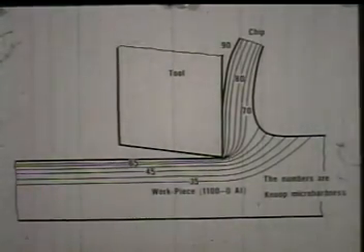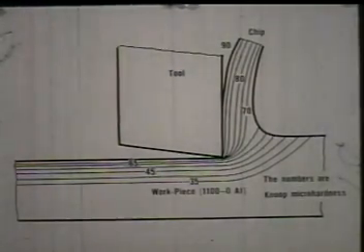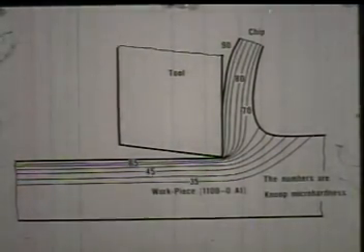The numbers on the lines indicate the location of the material that is strain hardened to Knoop hardnesses of the amount indicated. Although the hardness of the machine surface itself is not shown on the sketch, the hardness at a distance of 1 or 2 thousandths of an inch beneath the surface is approximately 70 Knoop. In the chip, hardnesses as high as 90 Knoop can be found.